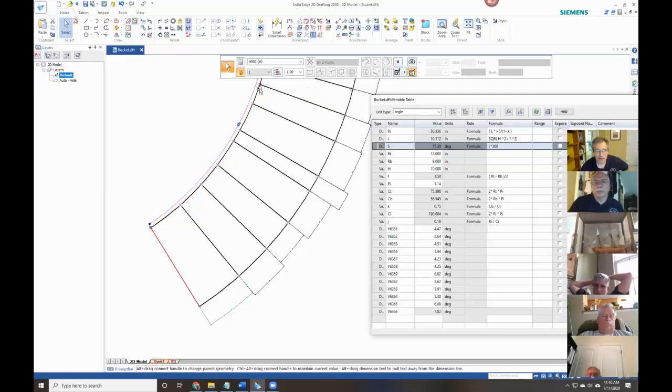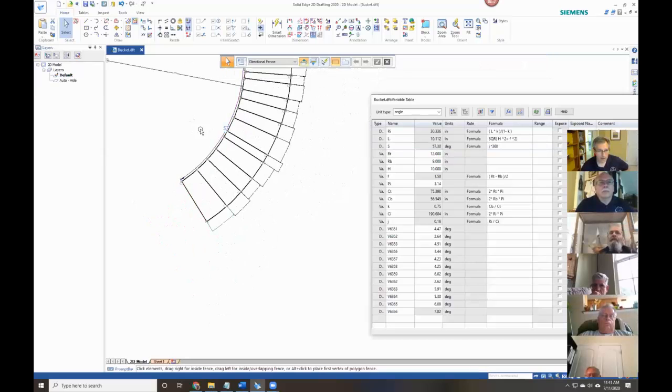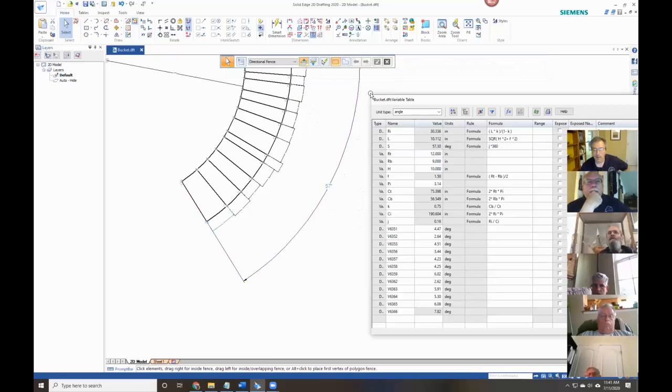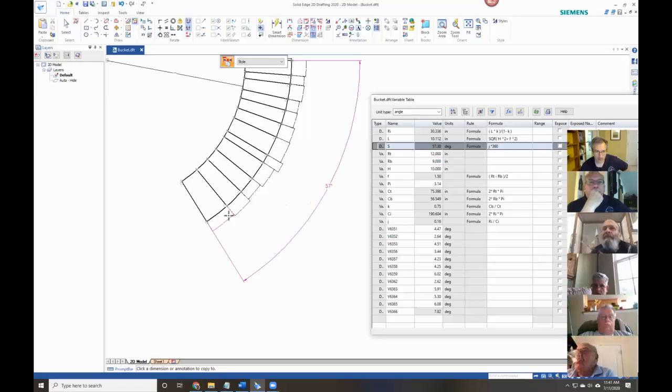Let's do one thing here. Let's change the size of, that's too big. All right. Size of our text. I should be able to, there we go. Can't read this, so I changed the size of the text. If you select it, this is the text size here. I can copy that to everything else by using this command, which is copy attributes. So I start that, I click the one I want to copy from, and then everything oh,